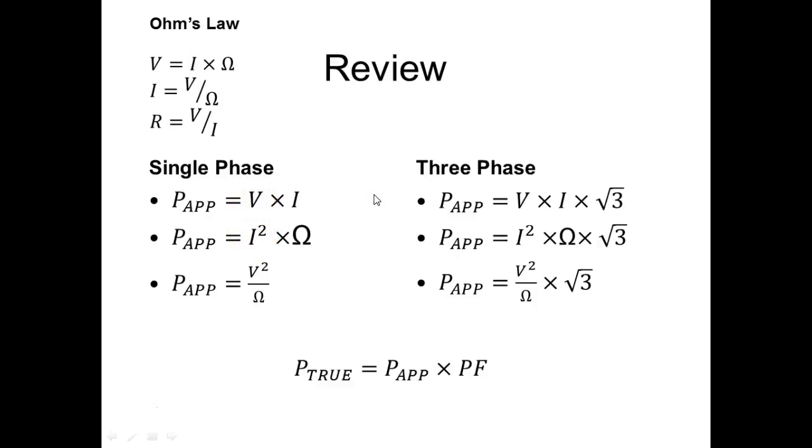Or I squared ohms. Now, why we use ohms here is a lot of people don't understand that we have two types of opposition in an AC circuit or a communication circuit. So in communication, everything is changing, right? You understand that? So that means communication, even if it's digital, acts like AC because it's constant change. And then this is where we add that thing we call impedance, where we add reactance, which are the devices that vary with frequency. Are you okay? So all opposition in a circuit is rated in ohms. So reactance is rated in ohms. So what is reactance? Well, reactance is opposition that varies with frequency.